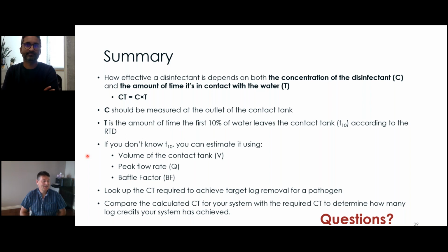Okay, thank you. We have another question here with regards to breakpoint chlorination and its relation to CT, and are they completely separate concepts from each other? Yeah, it's a good question. So breakpoint chlorination has to do with, if you're using chloramines, you're adding free chlorine and it's reacting with any ammonia that's in the water to form your different chloramine species, or it's reacting with other substances in the water, so it's using up that free chlorine. So you get that kind of breakpoint happening, and then your free chlorine amount is increasing afterwards.